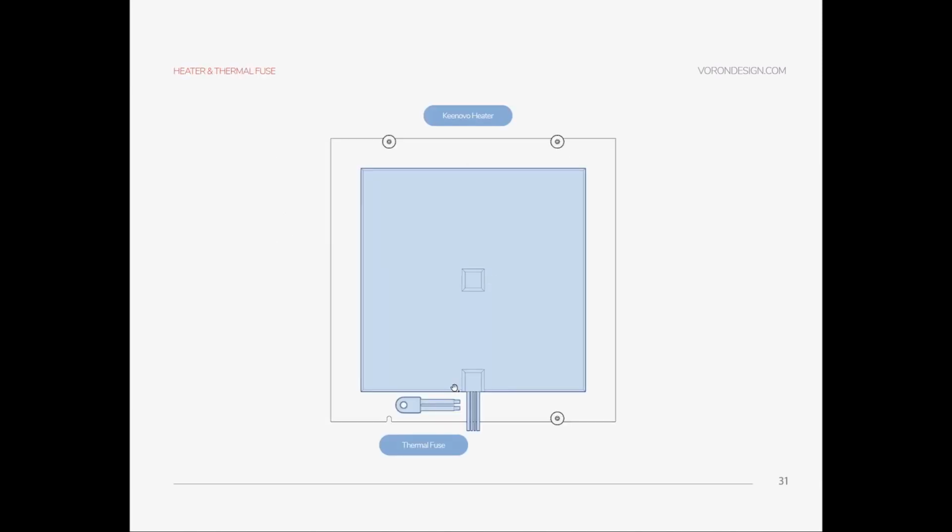So yeah, in the build plate you have an aluminum bed, a silicone heater, a thermal fuse, and plus an earth connection. If they are not there, you need to drill two holes, one for the thermal fuse and one for the earth connection, and just put your silicone mat on the bed and wait for 24 hours with weight on it. And after that, do the same for the magnetic sheet on the other face. Again, put some weight and wait 24 hours.